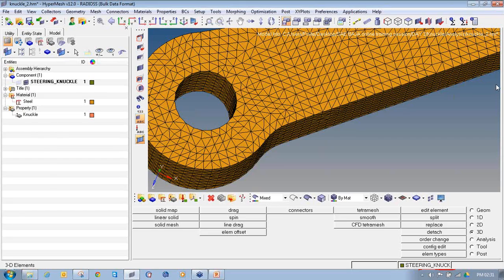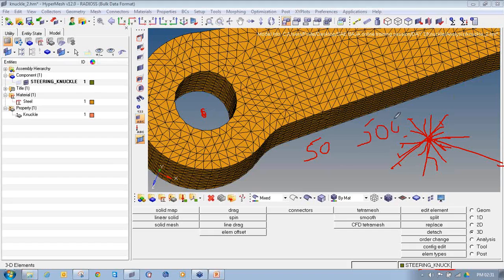So how does a rigid element get created? It creates some rigid links like this, a spider something like this. I will apply the force at this center node and it will transfer an equal amount of force. It will calculate how many rigids are connected through this node and divide the total force by that number and transfer it. So if you have 50 rigids connected with the center node and you have applied 500 Newton of force, then on each node it will automatically transfer 10 Newton.